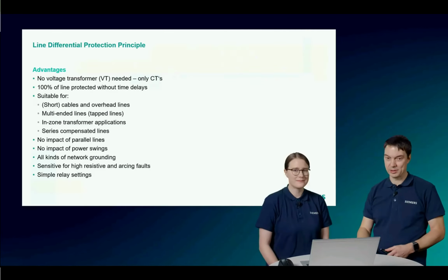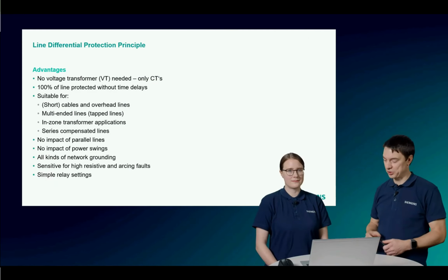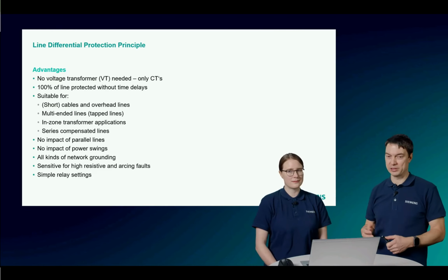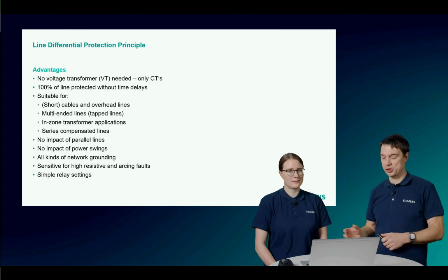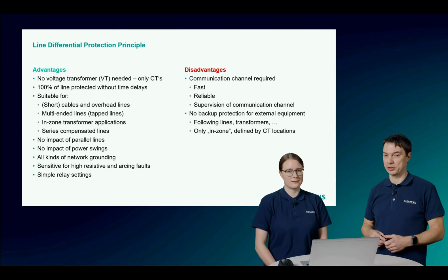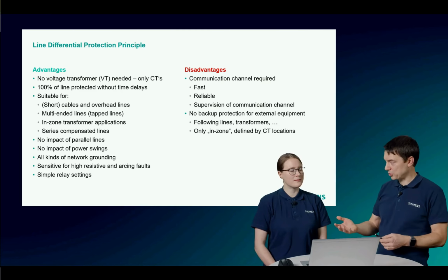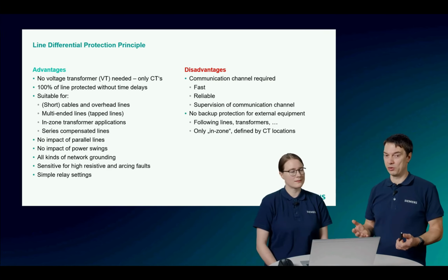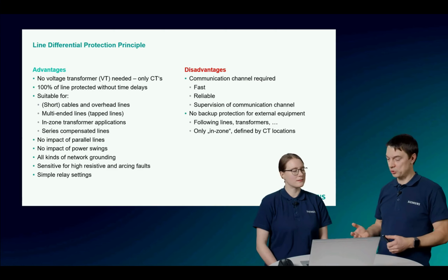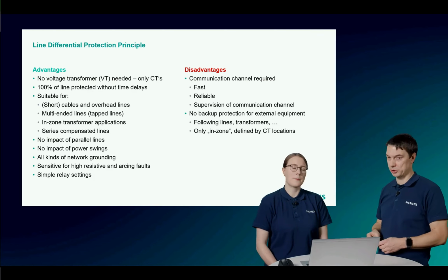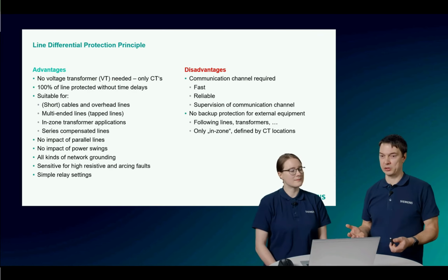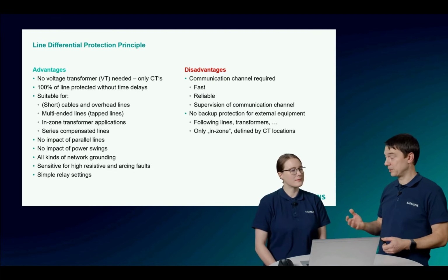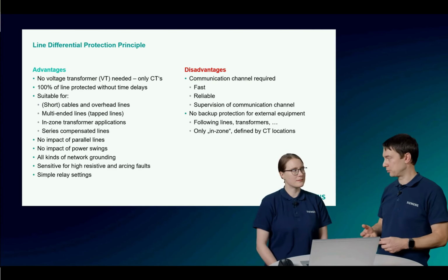Yeah, okay, as you know, the line differential protection and distance protection are two different protection principles. And what I presented in the first webinar were the advantages and disadvantages of the line differential protection, while the advantages are the disadvantages for the distance protection, and vice versa. If I say that there's no VT required for the line differential protection, then of course you need it in the distance protection. While the line differential protection requires, of course, a communication channel, which is not the case for the distance protection, at least if you are not doing teleprotection.